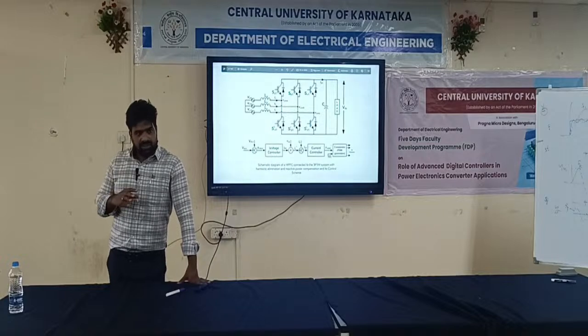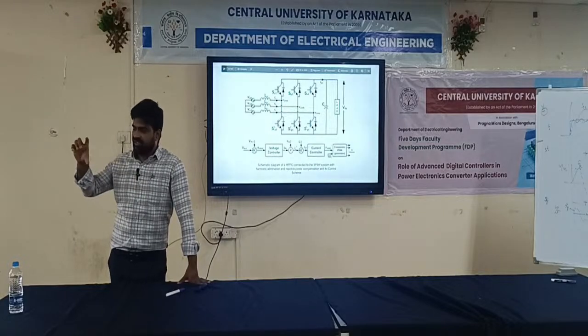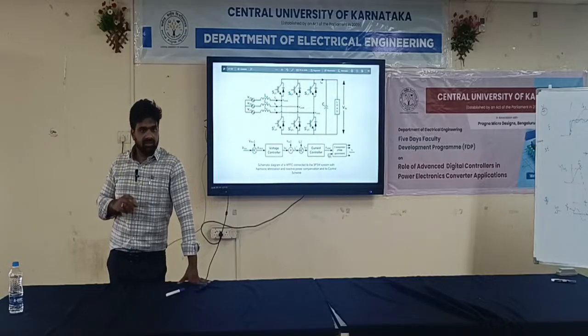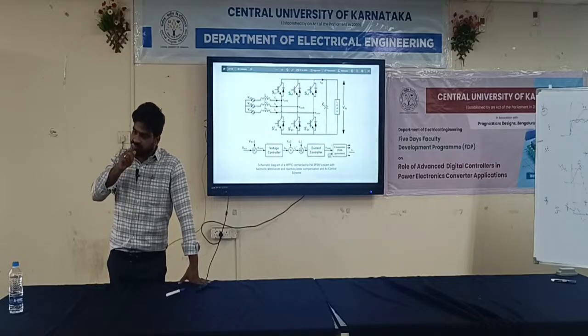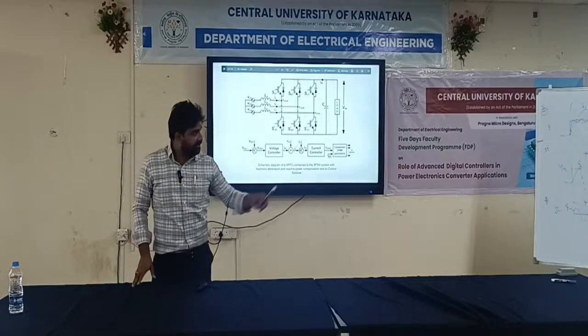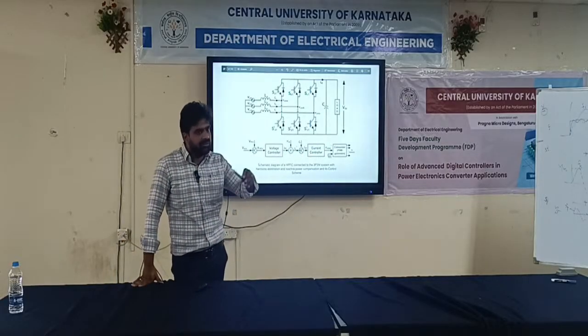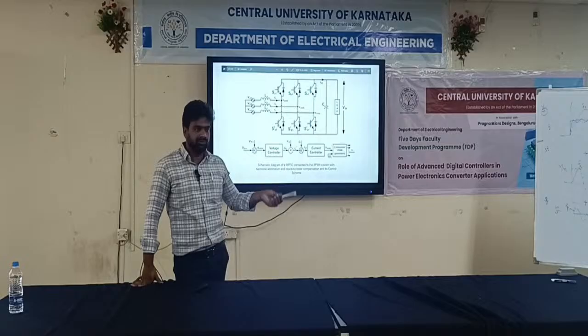Similarly, when you connect a rectifier and a DC load is connected to a DC capacitor to keep the voltage constant, when you change the load, the voltage drops. If there is no controller, the dropped voltage will remain the same. If you add more load, the voltage drops much more, and again it will be constant. And the 3 Vm by pi concept will again be in the picture if you are going for a rectifier.